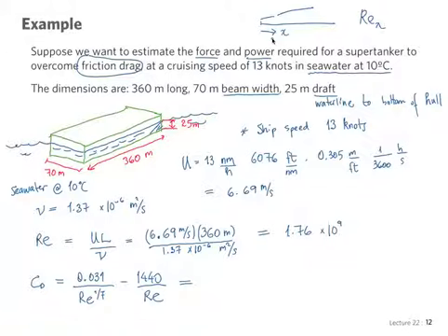So is this a more general equation than the other two? You would use this full equation, and if you calculate it and this turns out to be almost 0, it won't make much of a difference. But you need to see first. You need to put it in the equation and see first if it contributes or not, because every flat plate will have a laminar portion in the front and then a turbulent portion. Yes?